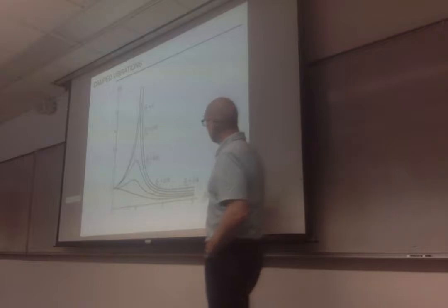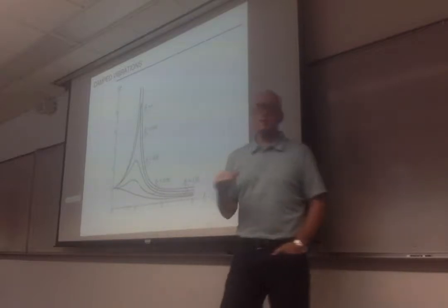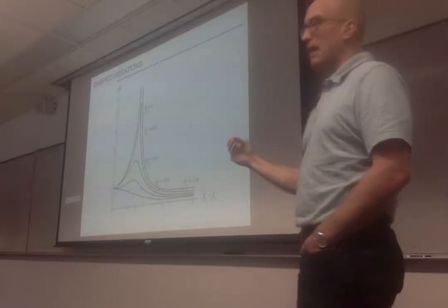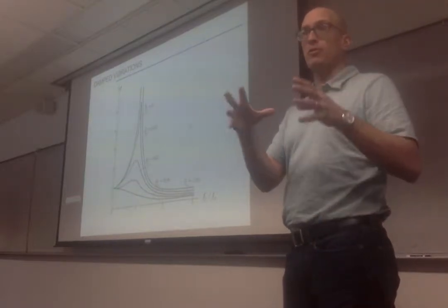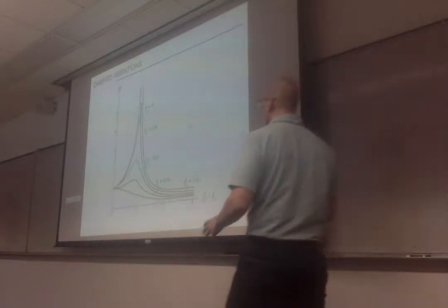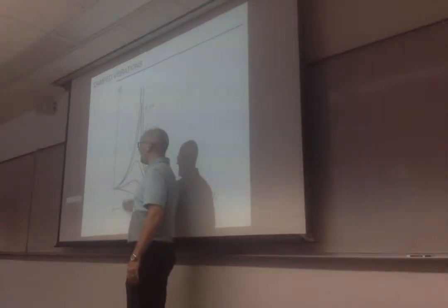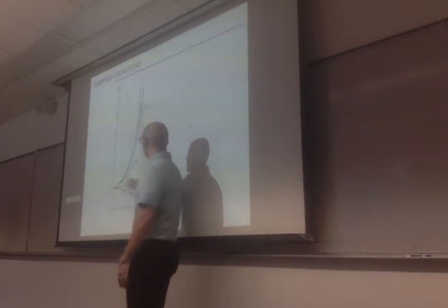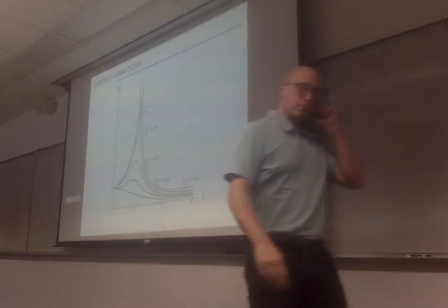That's what we were talking about earlier: even though you have some damping in every type of system, you're still potentially going to be faced with vibration damage if the natural frequency of your system is close to the forced frequency to which you are exposed. So that's still going to happen.